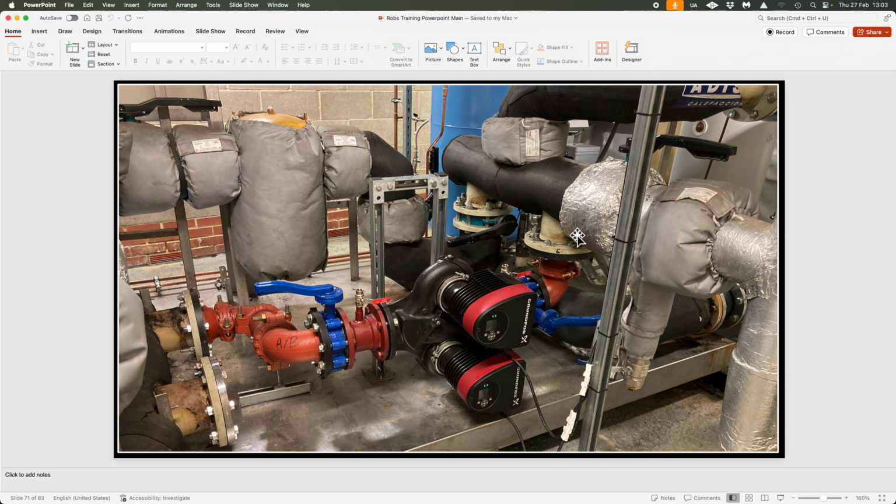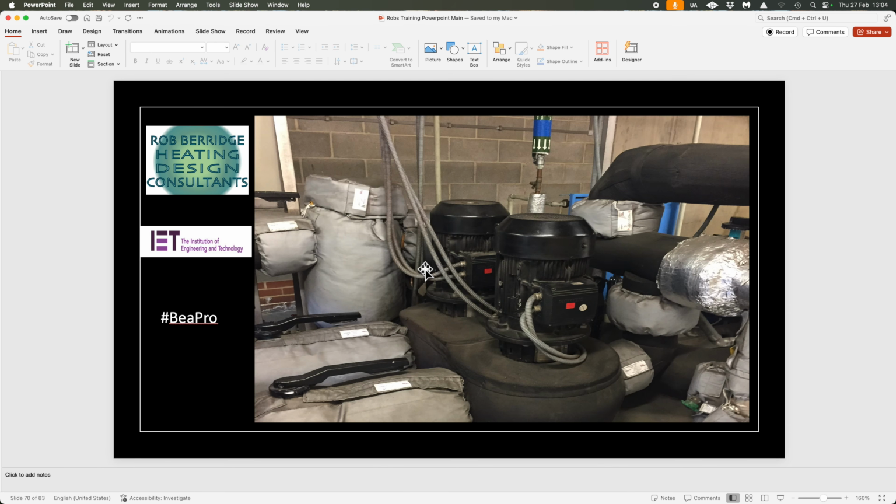So you can see that we've reduced the size down to DN 100 through here, and capped off one of these things from these 2 headers either side. So we capped off that first one, the flow's coming in here, straight down into the pump set and straight out. The difference is the cost of replacing these pumps. To replace the original pumps like for like, but with inverters and the installation, was nearly £100,000. It was a lot of money to actually replace these.